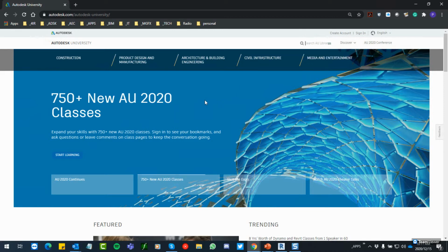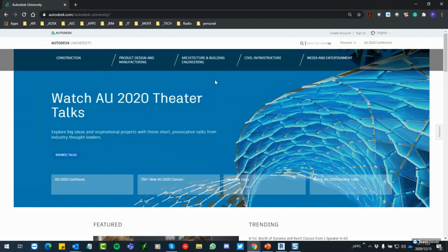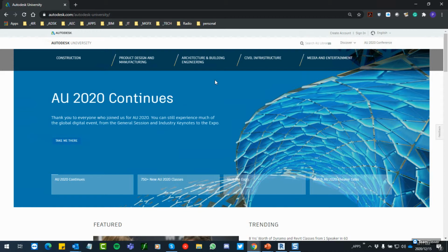Gert, there's a question: can you start your design in Robot Structural, or is it analysis only? No, you can draw things up in Robot as well. Typically it is drawn up in Revit to start with, and then brought into Robot. It's a great question. Something like a parking ramp, for instance, is traditionally very difficult to model up in Revit and to integrate into the structural model that you need to analyze.